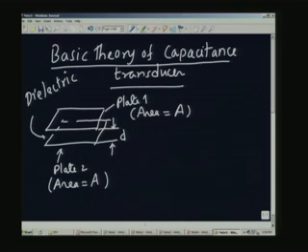In most applications of the pressure transducer, it may simply be air, or it may be some other fluid which may be there. The different materials which may be present here change the capacitance of the capacitor, because of the property of the particular dielectric medium which is going to be present there. Before we go into that, let me just write an expression for the capacitance.